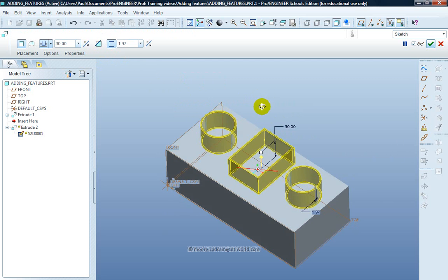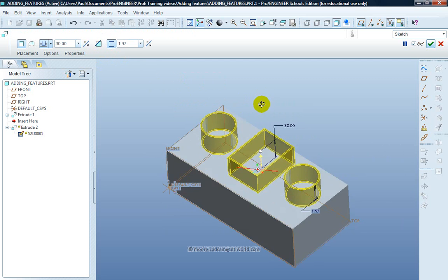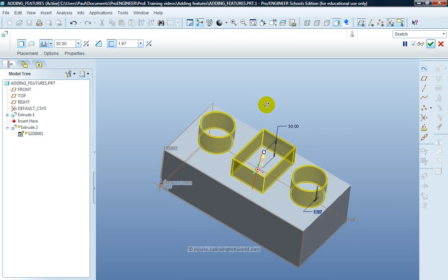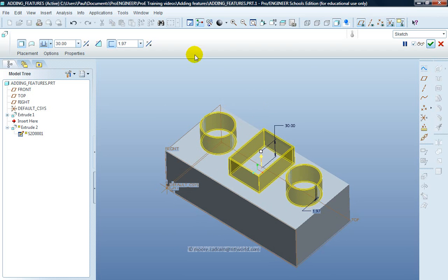You notice now if I hold down the central mouse wheel and move the mouse, I can rock the shape to actually see how it looks. So I've now got wall shapes there, and I can set the walls of those whatever size I want them to be. Let's say 3 millimeters, and I can do other changes should I want to. I could remove material by taking the shapes down into the block, but I'll do that on another side, and make other things as well.